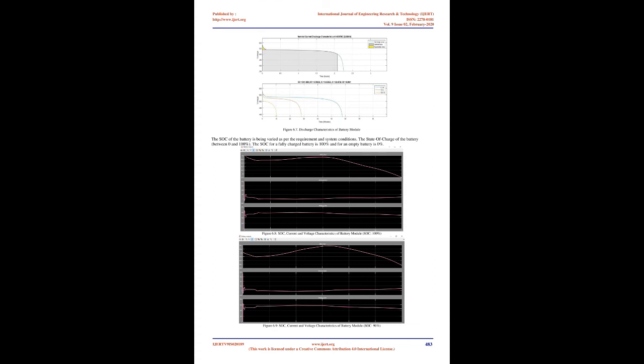5.4 Implementation of complete model of grid-connected PV system. The detailed model contains a PV array delivering a maximum of 150 kilowatts at 1000 W/m2 sun irradiance. A 5 kHz boost converter increases voltage from the PV natural voltage, 272 VDC at maximum power, to 500 VDC. The switching duty cycle is optimized by the MPPT controller that uses the Perturb and Observe and proportional integral regulator technique.